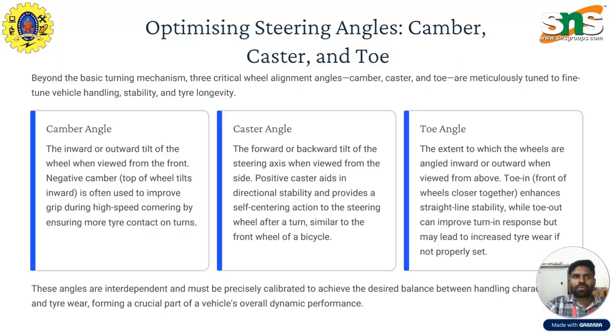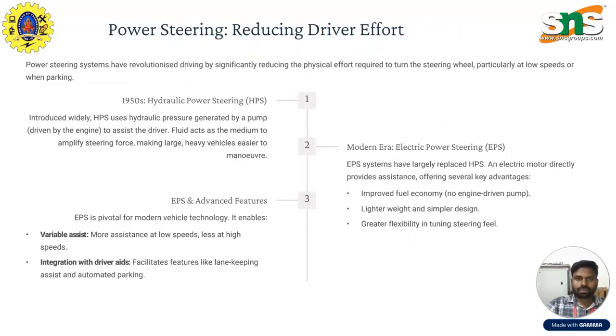Here we are viewing from in front of the wheel whether both front wheels point inward or outward. If towards the inside, it is called toe in, and if outward, it is toe out. Each possesses its plus and minus, and we have to control the angle of the tilt or toe in or toe out.